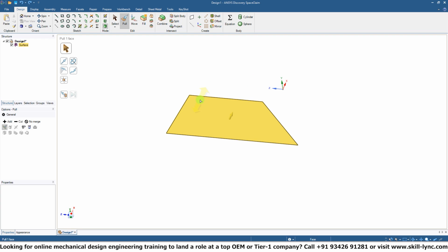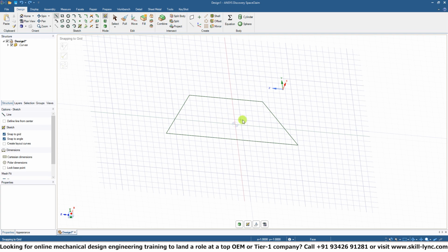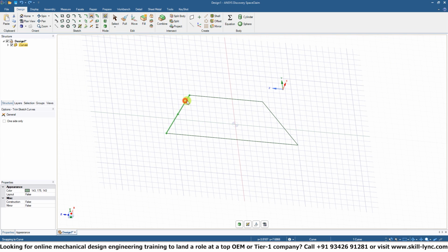Well, if we created the sketch, we could go back to the initial sketch and, using the corner tool, we can select these two edges and that will auto-complete the geometry for us, giving us the triangle we need.